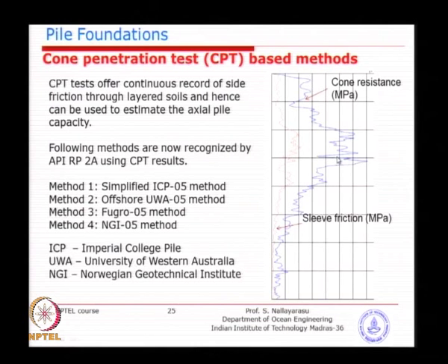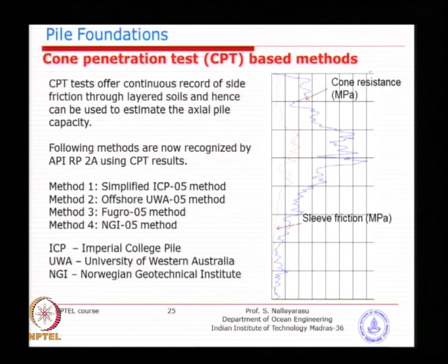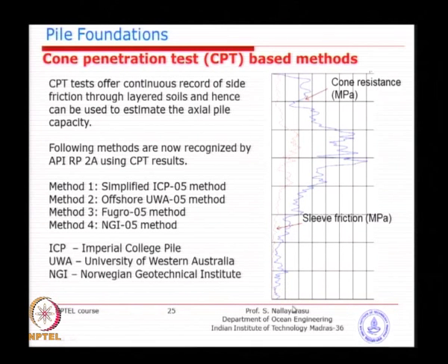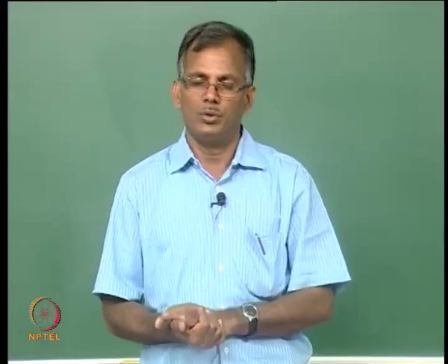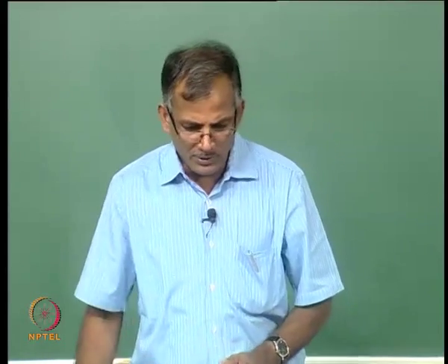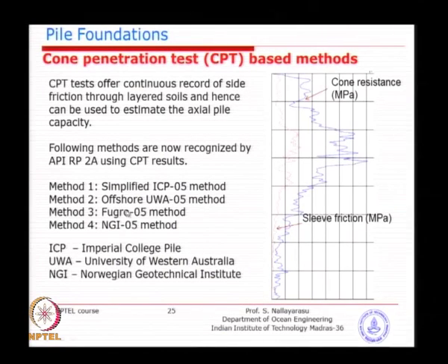But very seldom do people do it, because in deeper water depths as well as in deeper boreholes it is quite difficult, since cone penetration requires a lot of effort. Sometimes you may not get a continuous penetration. What will happen is, because the cone can penetrate say 10 meters, you will stop. After that you will excavate that soil, then restart the cone penetration. Then you need to interlink the top penetration with the bottom one. A little bit of difficulty is there, but established companies like Fugro have the methodology to connect them continuously.